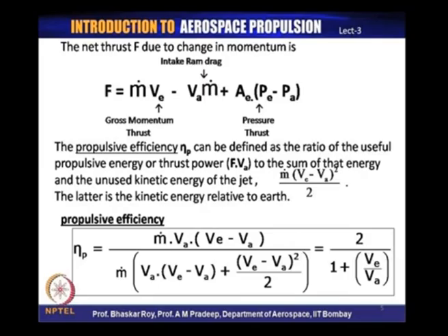okay, and thrust being now expressed in terms of power, and this is the energy that is available. So, this is again the thrust power, and this is the energy with which the flow is going out of the entire propulsive device, and this energy will not be available for any propulsive purpose anymore once it exits the propulsive body. And a simpler derivative of this full form appears in a very simple form over here.